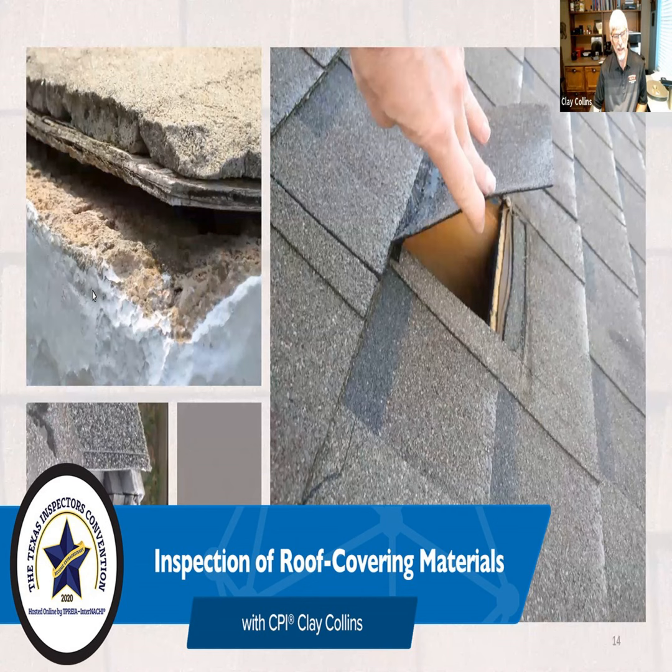If you do it wet, the wet underlayment on top of the roof deck, you're going to have possible deterioration of the roof decking. Remember that the underlayment is not only to provide a secondary drainage path, it is intended to protect the roof deck from the shingles and the roof shingles from the deck because of the way those materials can interact.